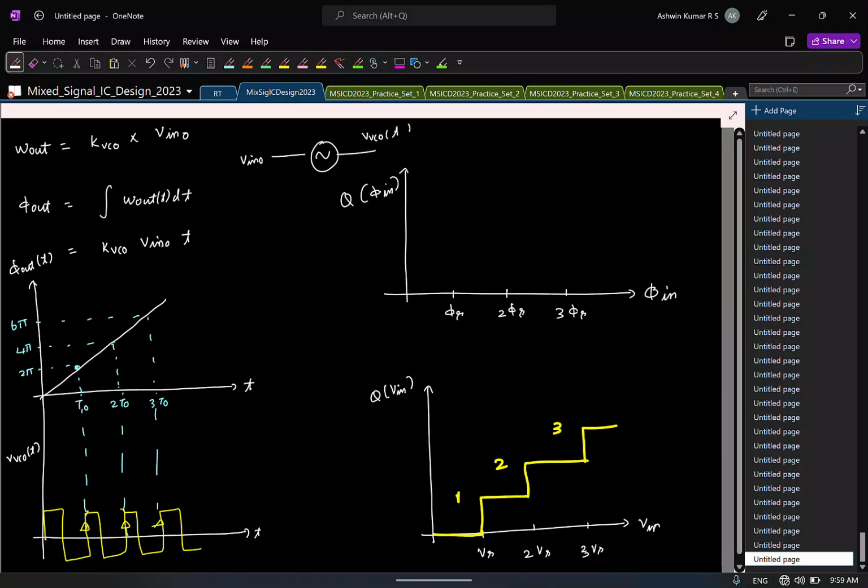In principle, this can be anything, but remember that the phase is not something that we can visually see. This is a hypothetical signal that you make sense of by looking at the voltage waveform. So you should choose a reference phase such that by observing the output voltage of the oscillator, you are able to understand what that phase is.